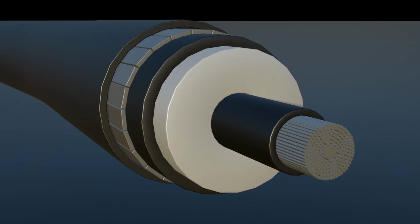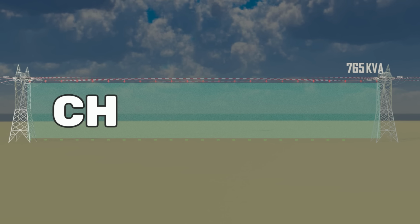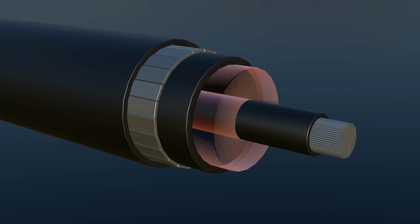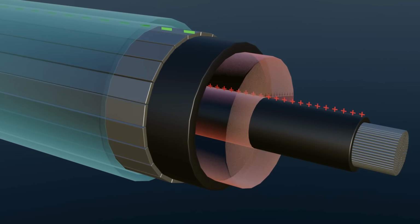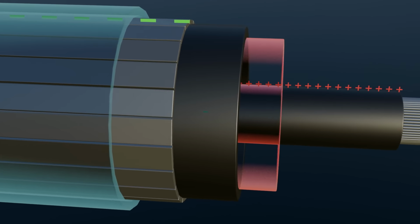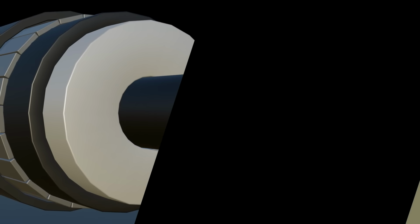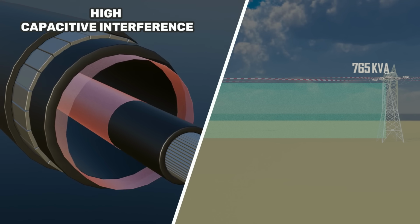Here, XLPE insulation sits between the conductor and the metallic screen, just as air acts as insulation in an overhead line. But inside the cable, this gap is very small. As a result, a capacitor-like effect forms between the conductor and the metallic screen, and capacitive interference appears again. If we compare an overhead line with a cable, capacitive interference is higher in the cable.